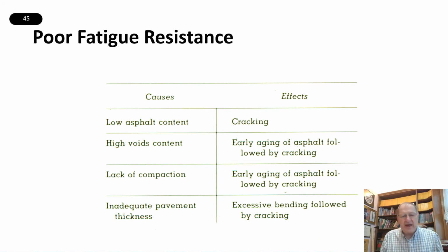and the engineer comes back and says, well, you need 8 inches of hot mix. And it's like, ooh, yeah, that's more money than I really have. And say, well, could we do it with 5 inches? And the answer is yes, you could. Now, it'll work, and it'll work fine for a while.